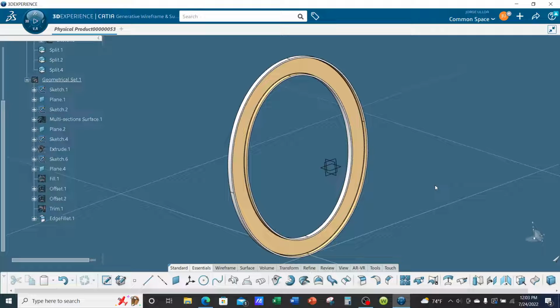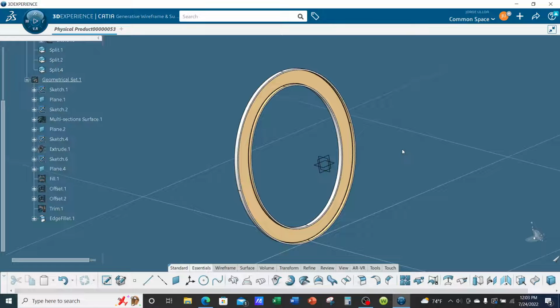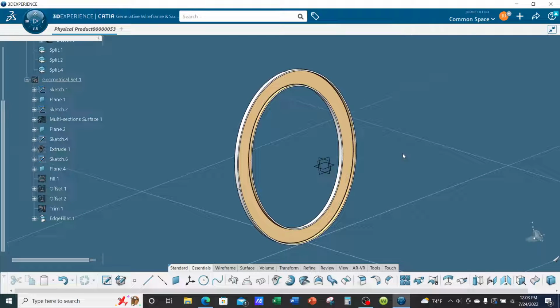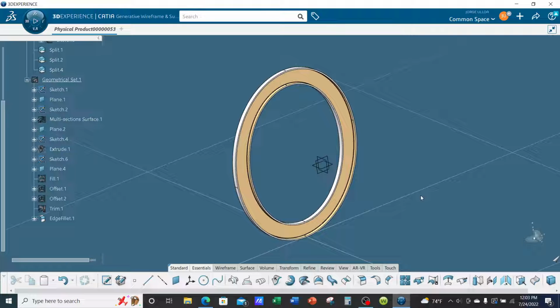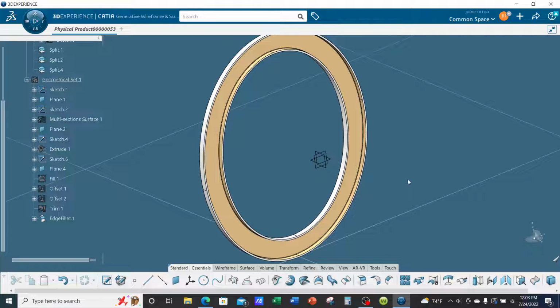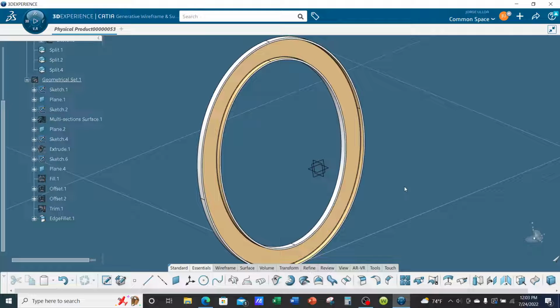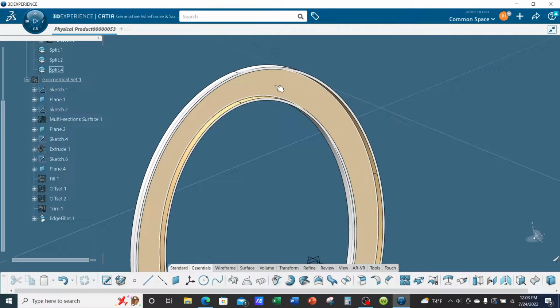Now let's say you turn this over to the stress analyst and they come back and say, hey, we need to make this lighter, right? So upper management says the aircraft is too heavy. Go back and analyze and see where we can remove material, make the aircraft lighter. So let's say the stress analyst tells us, you know what, we're going to make this even thinner, but only in the lower portion. Let's say the top portion, we want to keep it at 1/2 inch thickness.